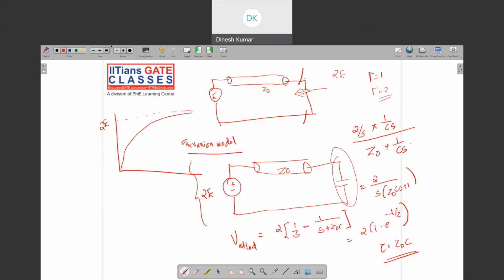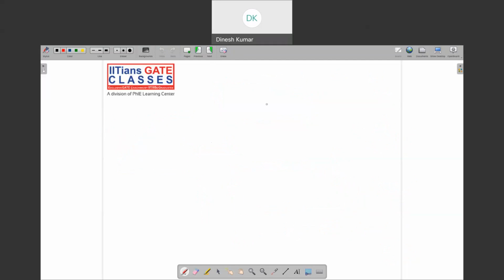Now we can think about what if we connect an inductor. So this is the surge, I'll put something like this, and basically the transmission line. A very high frequency surge is coming to the inductor. Now we can study the model. Assume that this is 1 per unit, something like unity. If you apply Thevenin, this will now become 2.